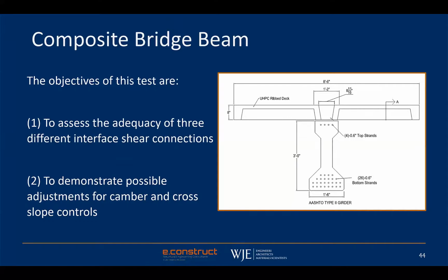An interesting exercise is what we're doing at Standard Concrete Products, and thanks to SCP for that. We had them make a type 2 beam, ultra high performance. We didn't introduce the web. And we had them also make precast deck panels separately, and we connected them in the plant before they got shipped.